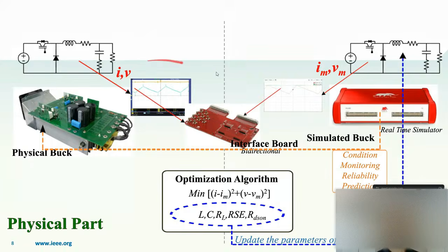We know that with this technology you can try to avoid or postpone failure of components with a more realistic model. We know from the people from reliability that DC capacitors and power semiconductors are prone to failure, and they have models for the lifetime, so we can use it in our favor and try to modify the controller if we identify something that is causing a dangerous or a stressful situation to the capacitor. As a result, components can be replaced before a breakdown happens.